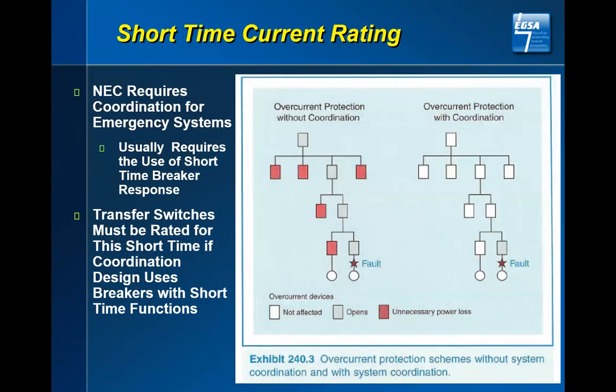This is what I was getting to with the comment of selective coordination. If you look on the left side, where the fault is all the way down on that bottom, if you are not coordinated, you notice I have taken out all sorts of feeders that I did not need to trip. Those ones in red unnecessarily tripped.